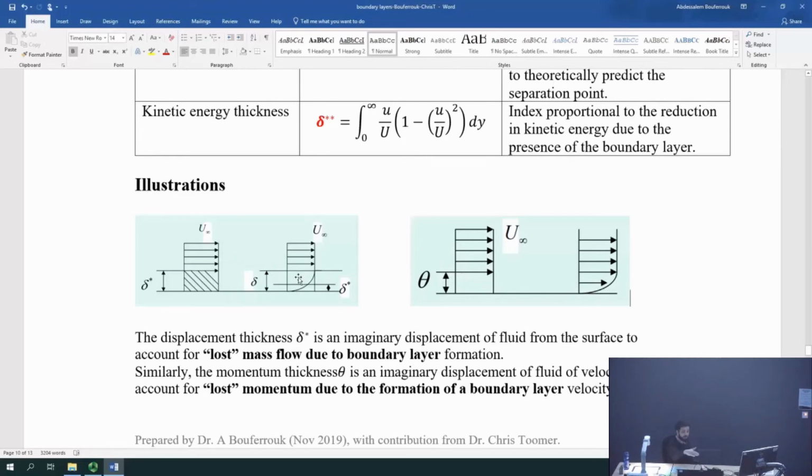Now once you have a surface and you create a boundary layer, which changes from zero velocity, the no slip condition at the wall, to u infinity at some height delta, the boundary layer, because it's physically sitting there, kind of pushes the streamlines, as they would be if inviscid, up. It displaces those streamlines.